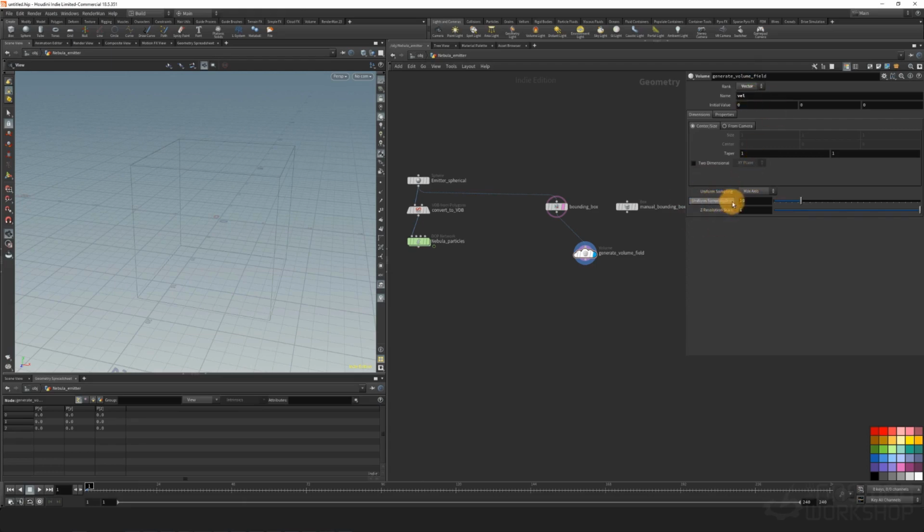Inside the uniform sampling subdivision, that's the amount of subdivision to create the voxel inside. So you know, it is the same. If we say 10, it means that we have 10 subdivisions over each axis. If we say 100, we have 100 subdivisions. So it's more precise or less precise depending on the sampling subdivision. We are going to do the same with this one. So it is essentially the same thing. We are going to see how it looks in a few.